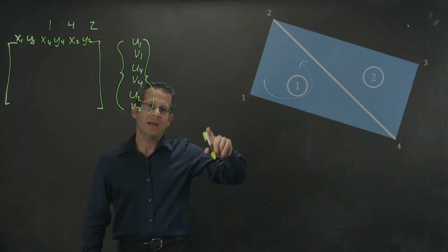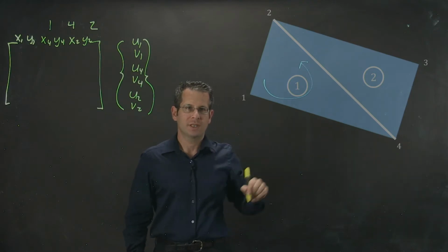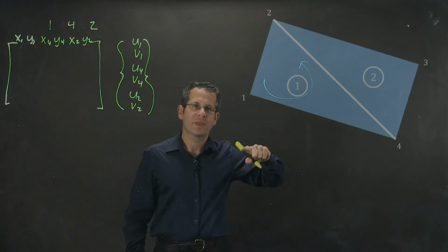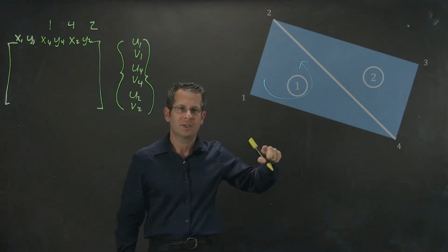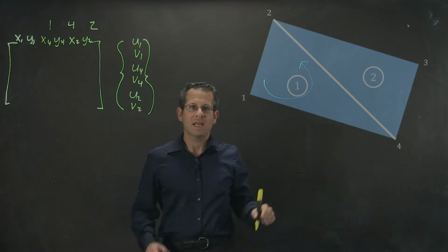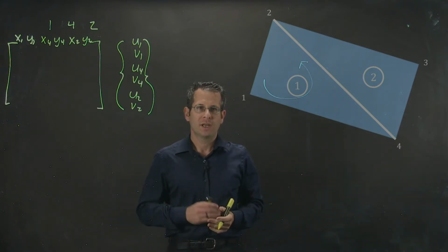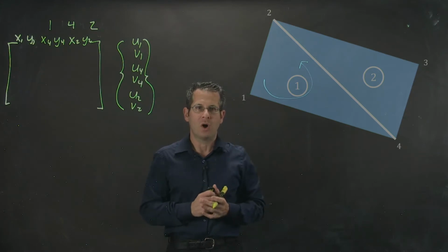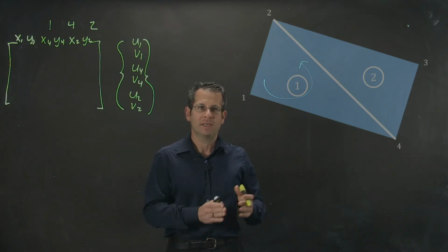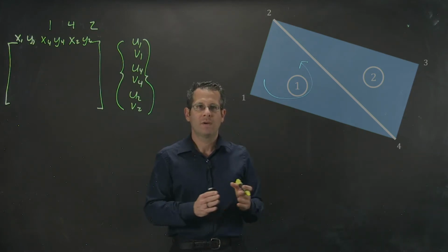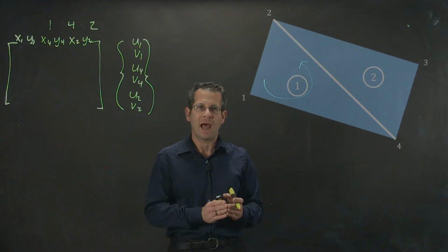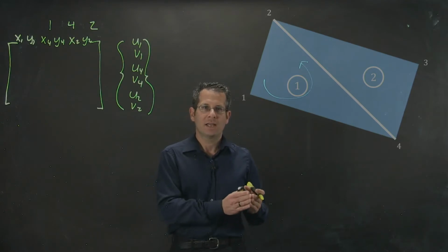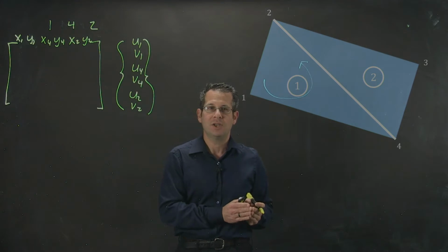The three force components, body, surface, and point forces, each component of those 6x1 vectors will all get summed together for a total equivalent force at the nodes, x component and y component for each node.